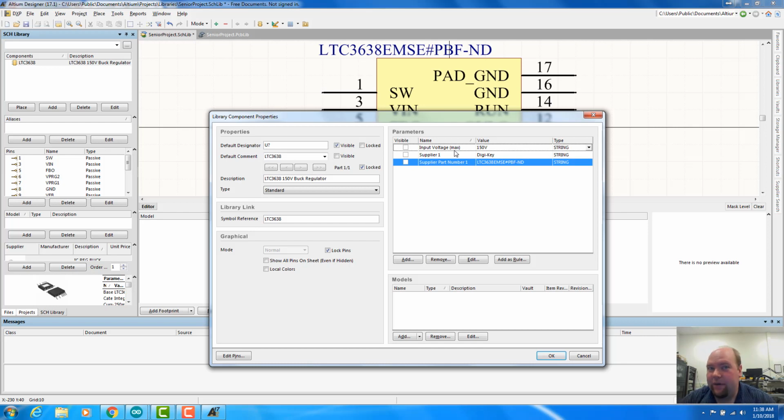Really, if you're working for a company, if this is an enterprise situation, you want to add a lot of detail to this. And a lot of it can be just taken directly from DigiKey. I would double check though. Always double check what DigiKey says about something against what it actually says in the data sheet, because sometimes somebody finds, you know, a bandwidth equals 2 megahertz in a data sheet, and they say, oh, okay, the bandwidth for this is 2 megahertz, but really the data sheet was talking about something else. So make sure to double check. If there's something critical about a component, make sure to double check it on the data sheet itself.